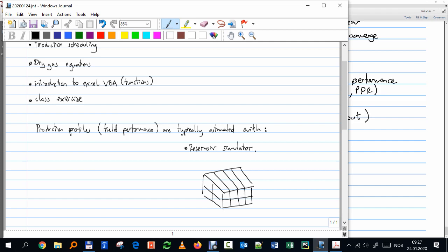Then I apply some sort of mass conservation equation between each block. Each block has a certain amount of fluid and a certain pressure, and to compute the flow transferred between one block and the other, you use some sort of Darcy law, with permeability.